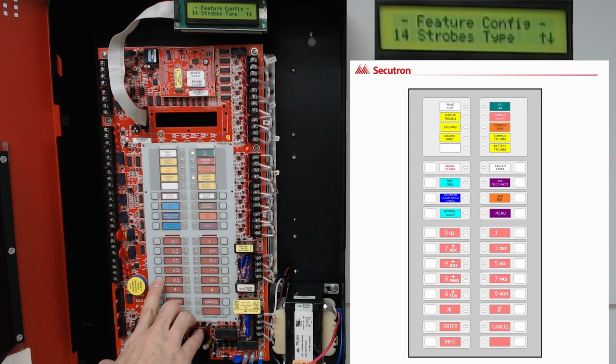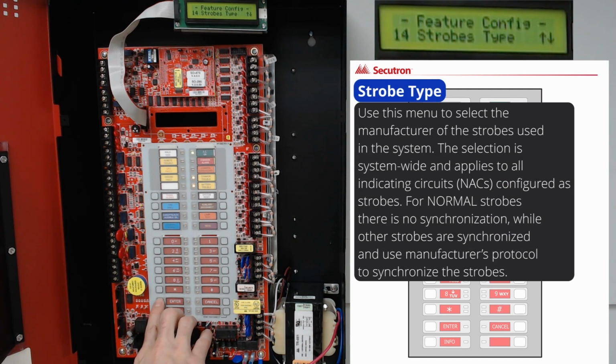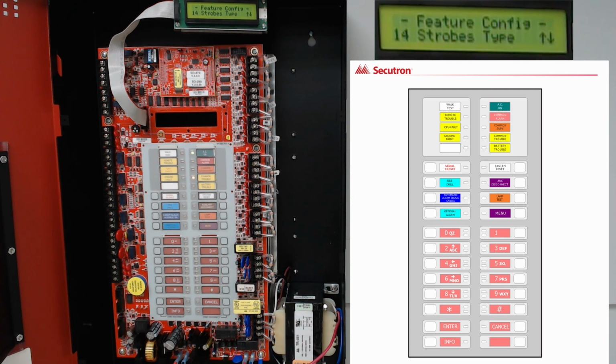Option 14 for Feature Config is Strobe Type. By selecting Enter on Strobe Type, we get to go through the options for it. By default, Normal has been selected. By pressing the down cursor, we can go through Gentex, System Sensor, Mircom, Faraday, Wheelock, Cooper. When we find the desired strobe type, all we have to do is simply hit the left or right cursor arrows to apply the X, Enter, and then Cancel to exit back out to the previous menu option.